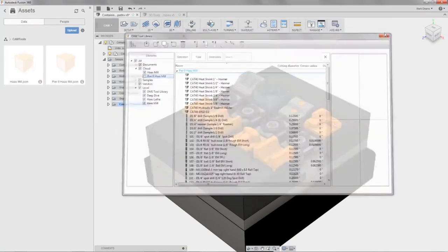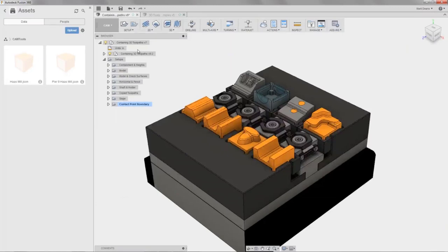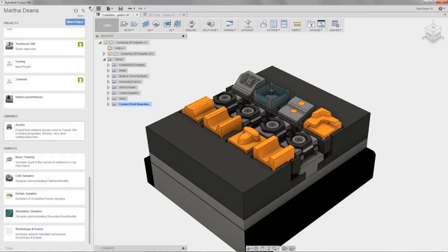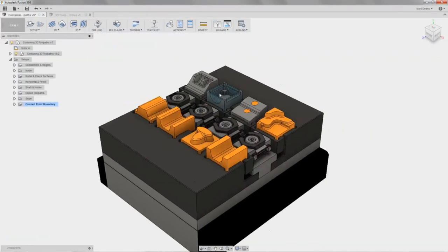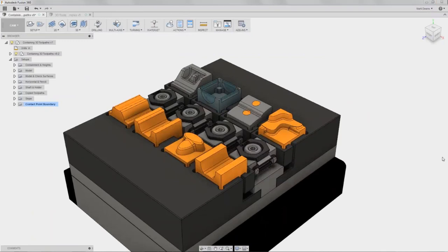So I can get tool libraries into Fusion also by uploading them to this folder rather than importing them in the tool library. And then the same goes for templates and posts, which we'll get to later. But just so you guys know, this exists now. It's another way to access your data and effectively be able to use and share it. Okay. So tool libraries.